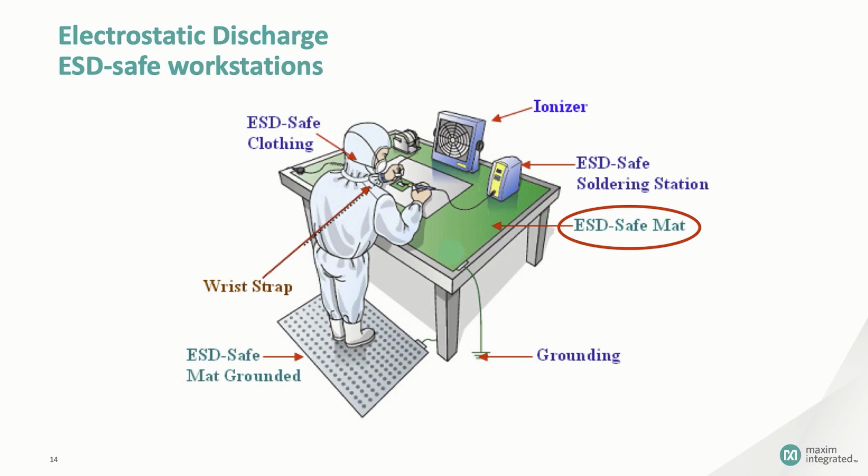Your equipment needs to be static safe too. Now, all modern soldering stations use a 3-wire grounding system, but be sure yours is also labeled as ESD safe. That guarantees that the mat and the soldering handpiece are going to be at the same potential. An ionizer is a helpful accessory. This device ensures that the air around the workstation contains a concentration of free ions that tend to neutralize accumulated static charges. Better to neutralize them before they can do something terrible.